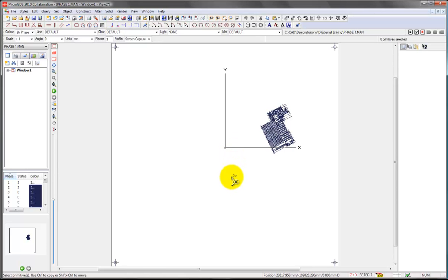I've found it simpler to produce these registration marks because I've discovered that there are some older versions of CAD systems that can actually shift the information around on different layers if their extents are quite large, as they would be with many master plans. So to overcome that, I make sure that these registration marks are placed on every layer in all of the projects that I work on.